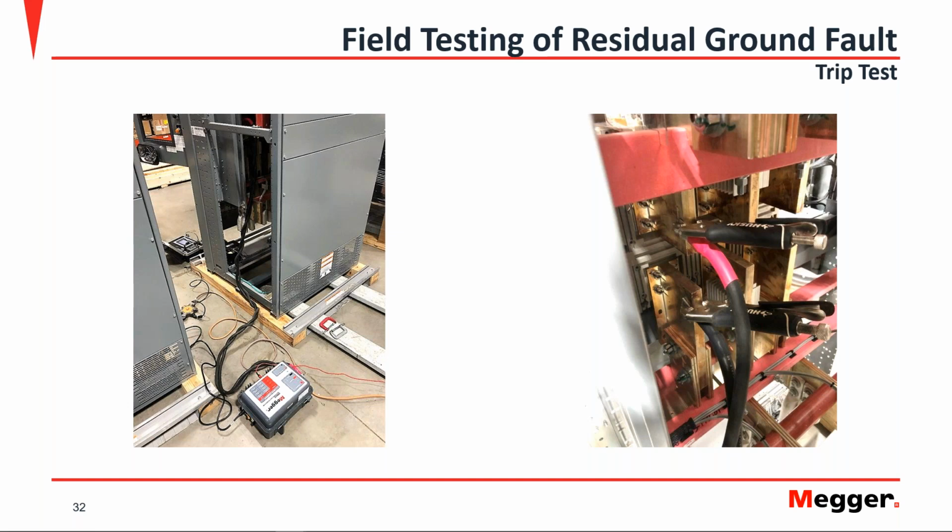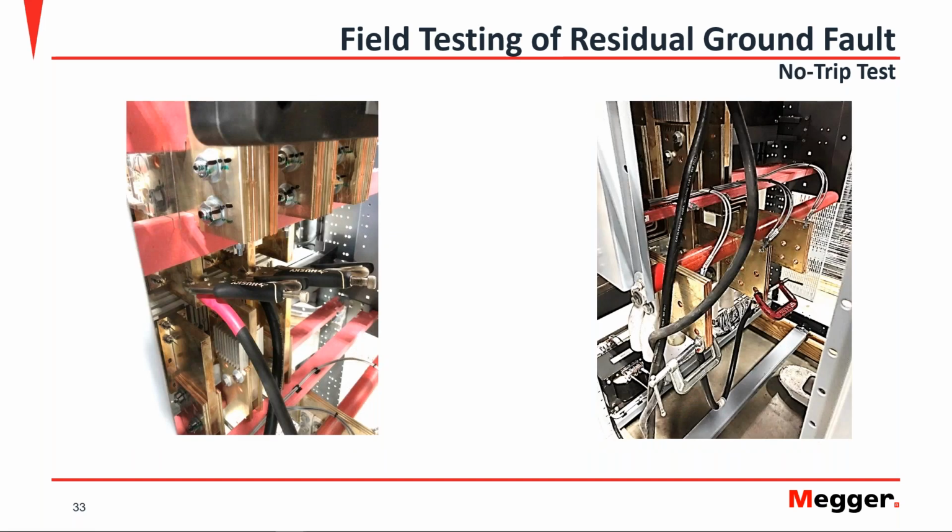Connections, as you can see, as I was mentioning, the length of the cable. In this example, we're using vice grips. Also really important, let me show you a couple more, either vice grips or clamps. Of course, we want to make sure that those connections are tight, that the contact resistance between my test cable and the circuit breaker terminal is minimized.